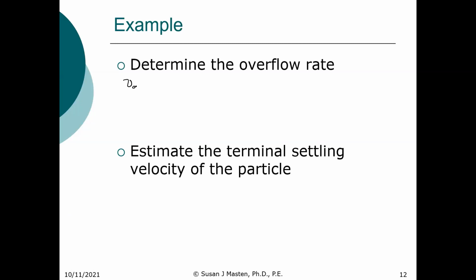The overflow rate is equal to the flow rate divided by the surface area. It is also equal to the height divided by the detention time.